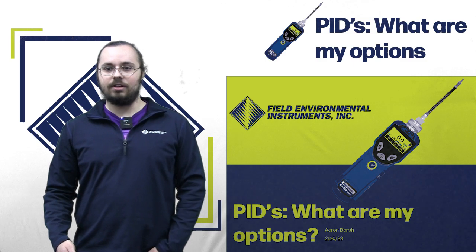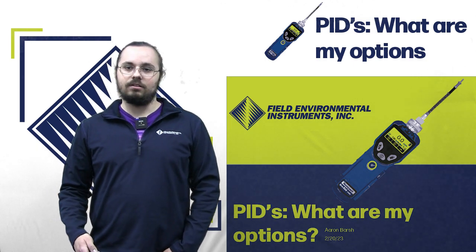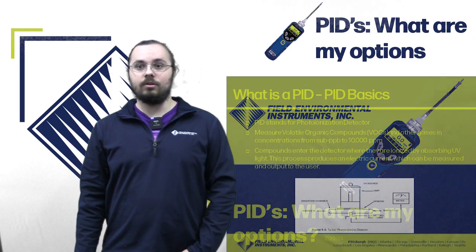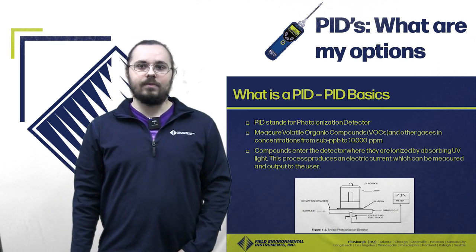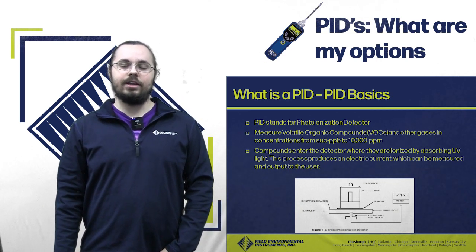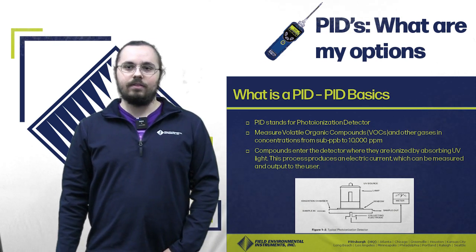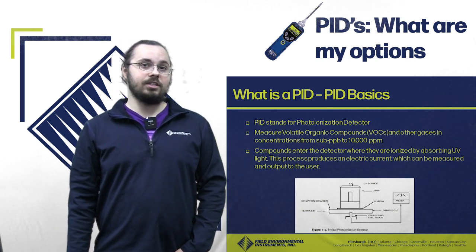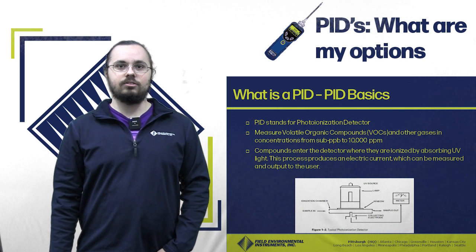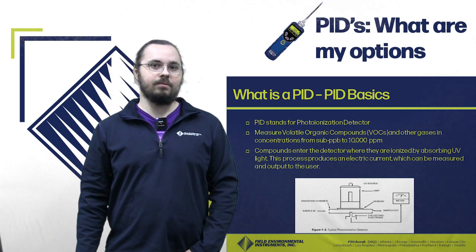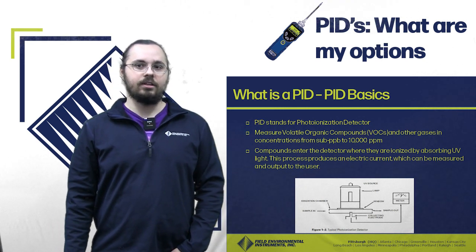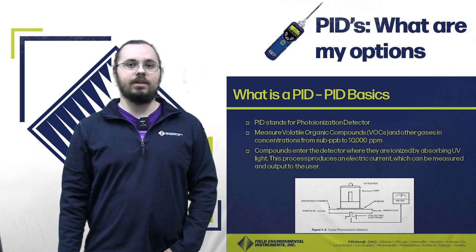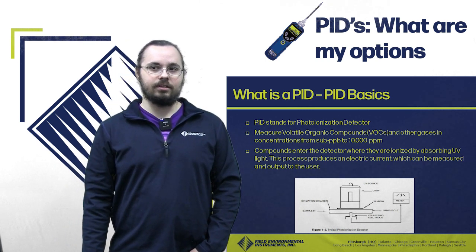Today, I'm going to be talking to you here about PIDs. So, what is a PID? PID stands for photoionization detector. These are used to measure volatile organic compounds, known as VOCs, and other gases in concentrations from as low as sub-ppb, parts per billion, to up to 10,000 ppm, parts per million.